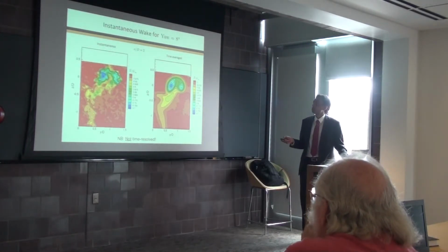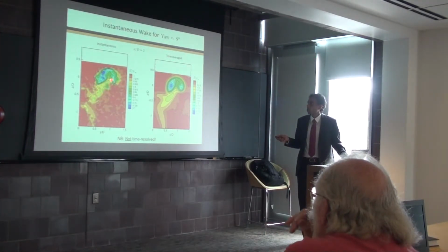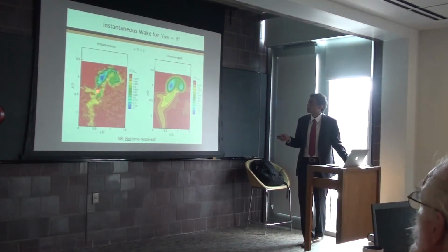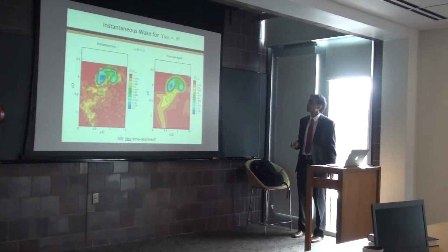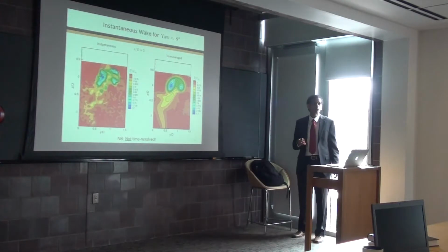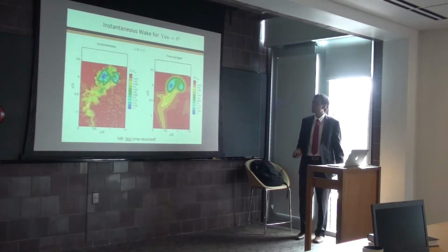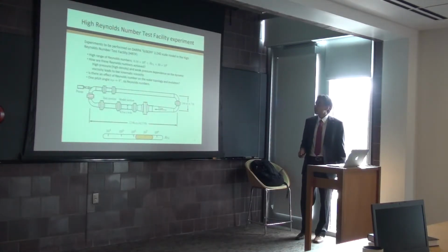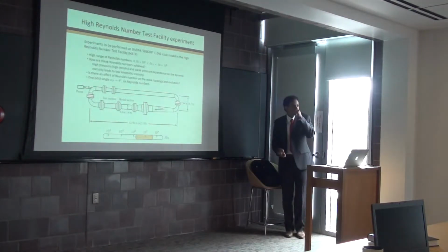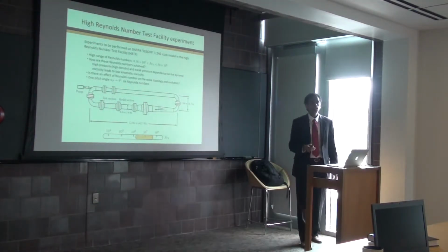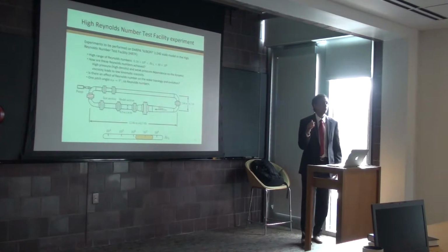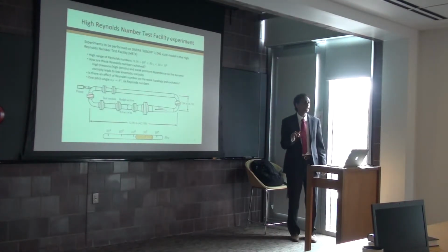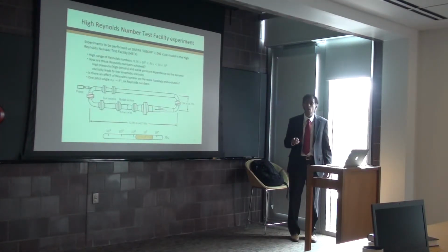And this is true not only in pitch, but also in yaw, where we can see that this wake is remarkably steady. This is, of course, all at a Reynolds number of 2.4 million, experiments performed in a low-speed wind tunnel. I mentioned before that we would like to extend the measurements from Reynolds numbers that are achievable typically in the lab, on the order of 1 million or so, to slightly higher. One order higher, if possible.